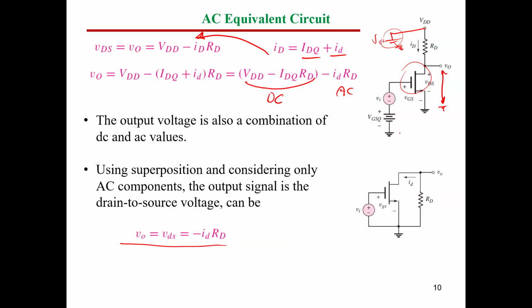And here in the gate side of the MOSFET, we have an AC component and a DC component again. Remove the DC component by superposition, so we will have only the AC. So this now represents our circuit. But this is the complete circuit, not the MOSFET circuit. So the complete circuit is we have resistance RD, we have ID flowing from the drain terminal to the source terminal of the MOSFET, and we have the input connected to VGS. So this is the amplifier AC circuit, but not the MOSFET AC circuit.